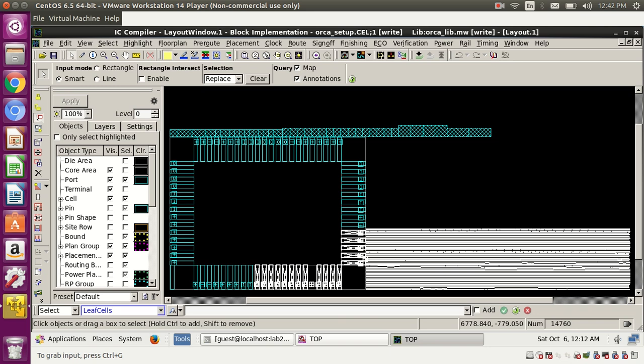We will explain this only in the interview. I think you all will explain the same. So what happens in the tool is that it will calculate the capacitance here. So this M3 and this M3, two plates separated with this much width, with whatever dielectric, spacing, insulator there is. It will calculate these two plates like a normal capacitor, with this much spacing, with oxide as an insulator, and work out what the capacitance is.